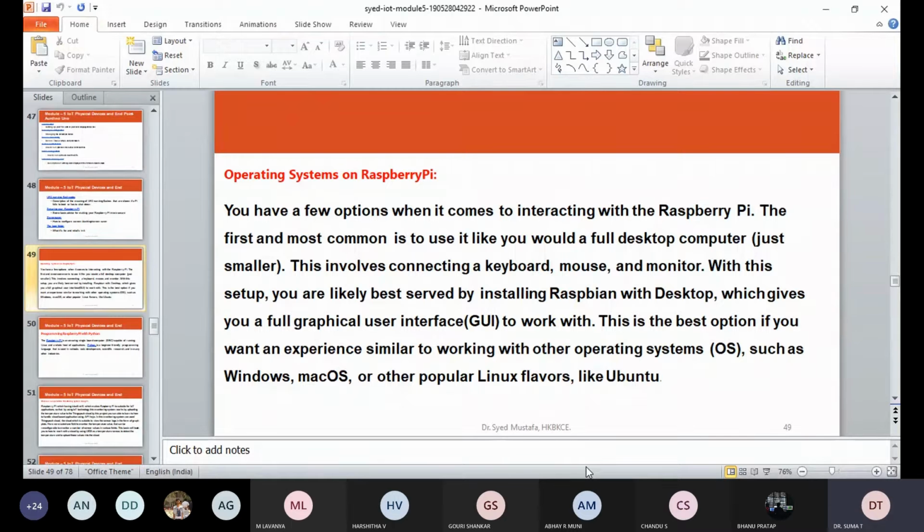Once the SD card has been formatted, drag all the files in the extracted NOOBS folder and drop them onto the SD card drive. The necessary files will then be transferred to the SD card. When this process has finished, safely remove the SD card and insert it into the Raspberry Pi. This is how we are going to install the operating system on the SD card.